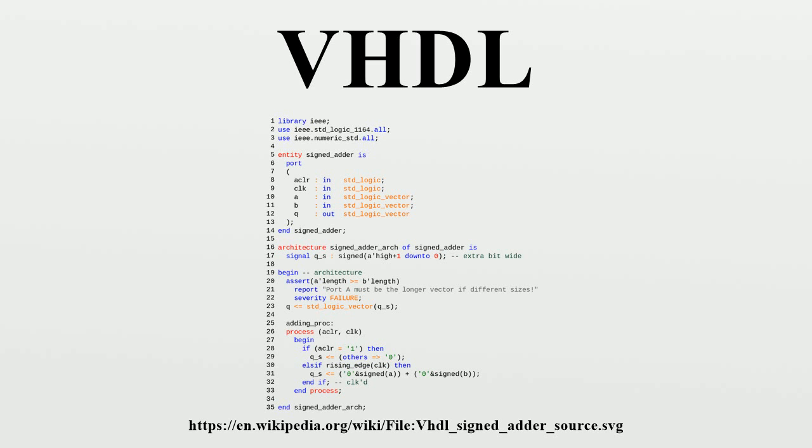Process begin wait until start = 1, wait until start is high; for I in 1 to 10 loop, then wait for a few clock periods. Wait until rising_edge; end loop. For I in 1 to 10 loop, write numbers 1 to 10 to data every cycle: data <= to_unsigned; wait until rising_edge; end loop. Wait until the output changes, wait on result. Now raise ACK for a clock period: ACK <= 1; wait until rising_edge; ACK <= 0, and so on. End process.